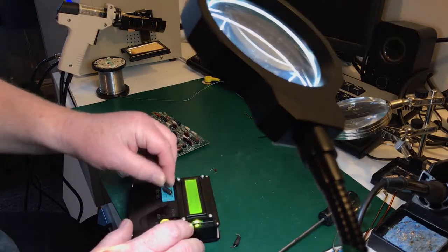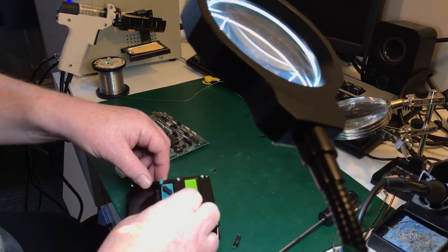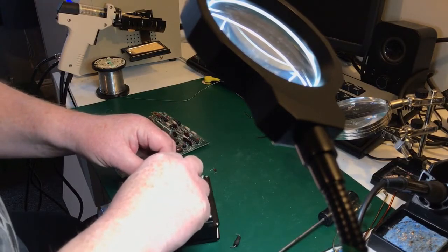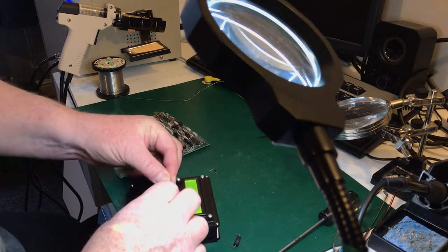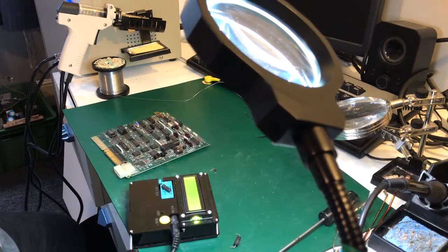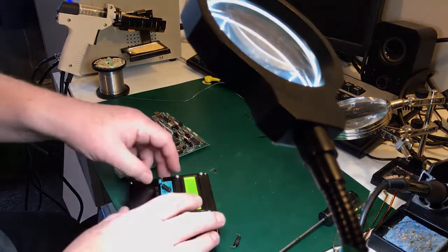That says no part, unknown, which is logical really. I can't see that being a working capacitor. So C22 is testing as maybe a 20 microfarad, 8%, ESR 0.07 ohms. Okay, it's possible it's still alright, but I think we'll just replace it. I might look at C24 as well, because that was around the area that was damaged.